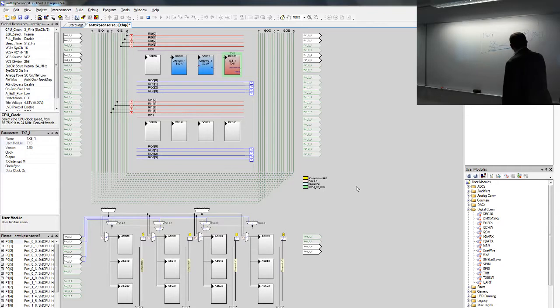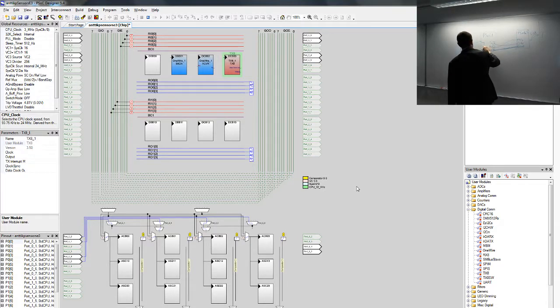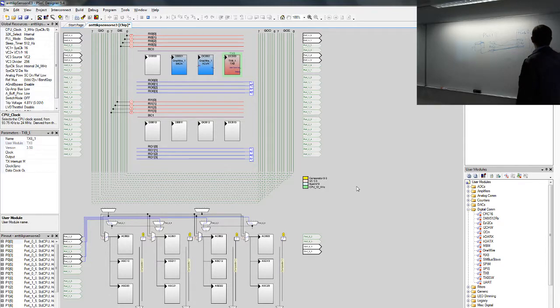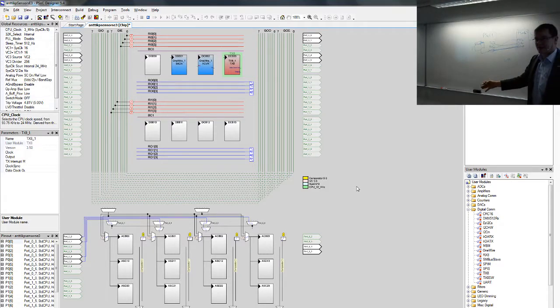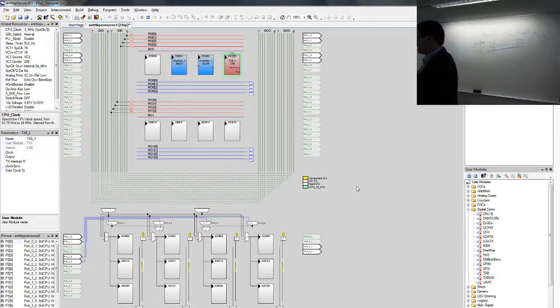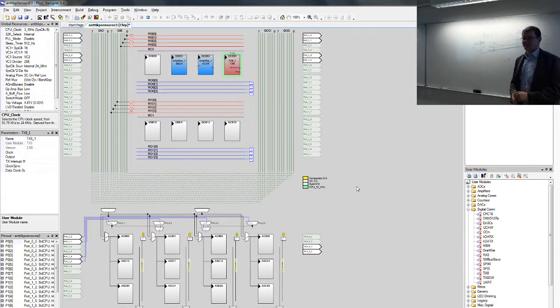So there's the mini prog, and that also goes to a USB port of the computer. There's no guarantee, especially on laptops, that these would be connected at all. Absolutely no guarantee. They can be totally separate. Most of the time they are not, but anyways, they are still a kind of long cable here and some open wires here, so if you leave that one out, you'll get common mode noise in between, and that'll disturb your data transmission. Okay.